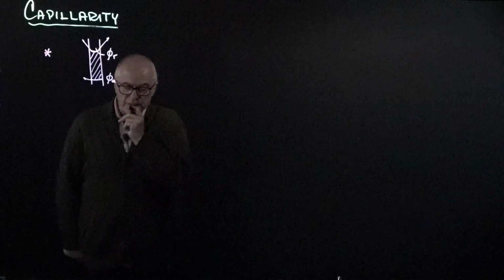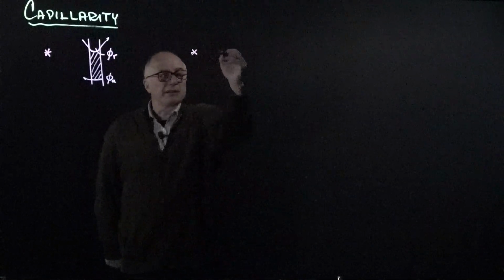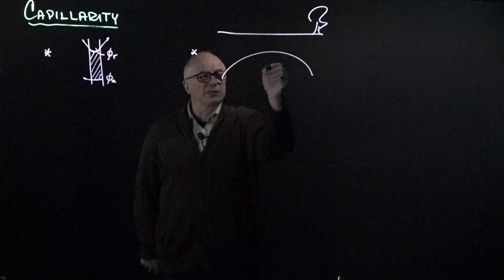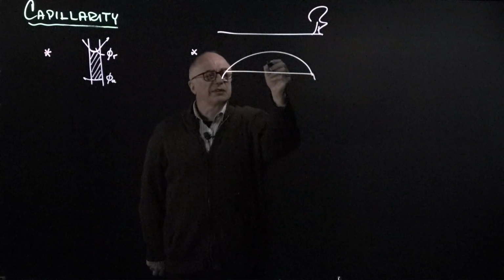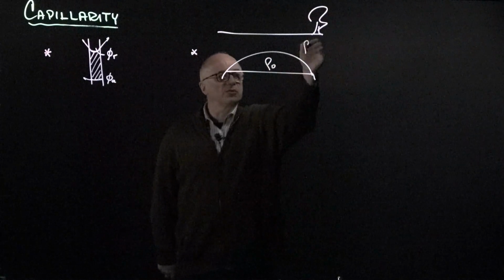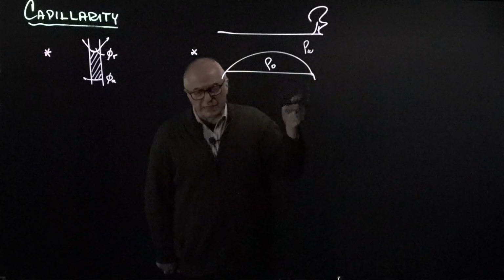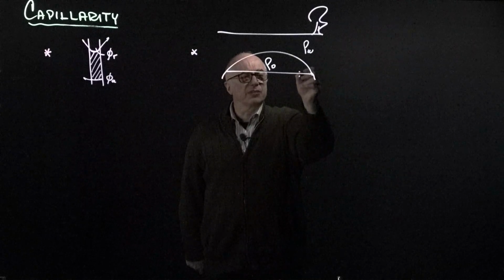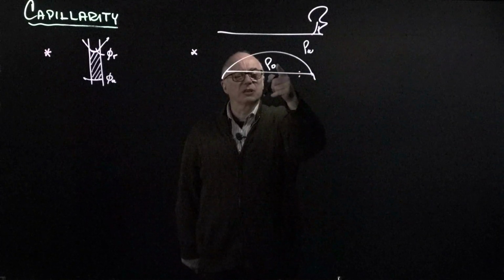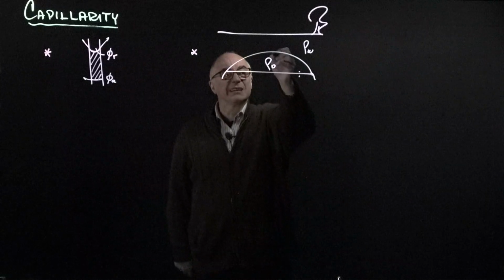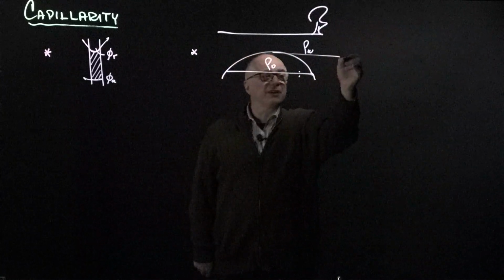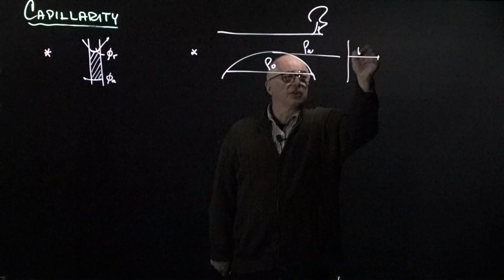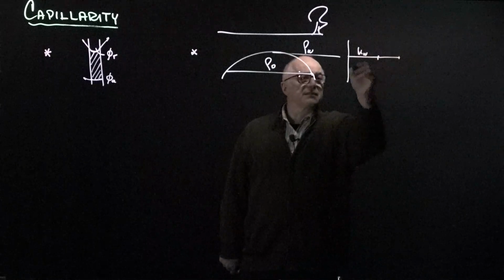Similarly, we can have another example. Let's assume that this is an anticline for an oil reservoir that is filled with oil. So this has the unit weight of oil, and this has the unit weight of water. If you go back to the analysis of effective stress, you will remember that because at this interface both oil and water have the same pressure, and because the mass density of oil is lighter than water, here at this interface the oil will have a higher pressure than the water. So this is u_water, while this is u_oil.